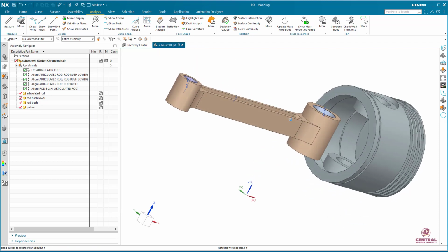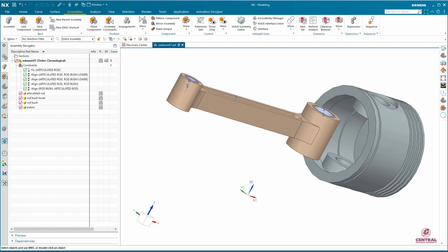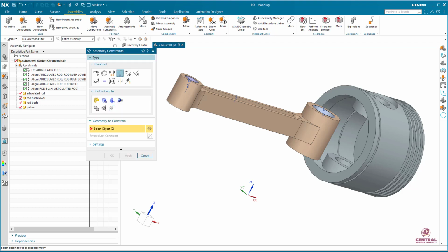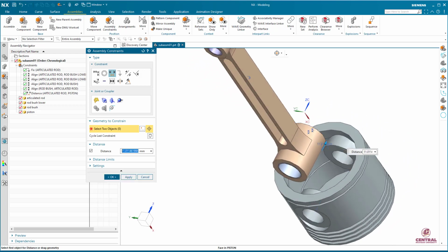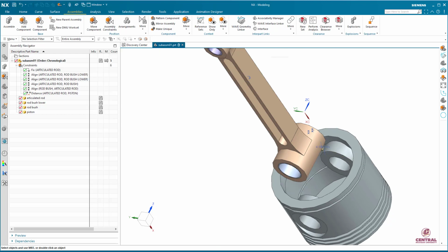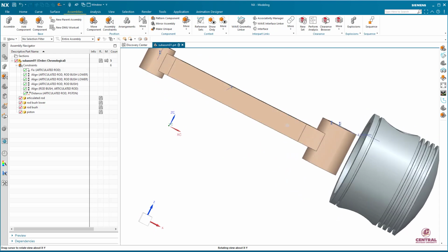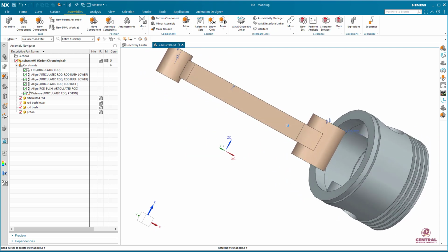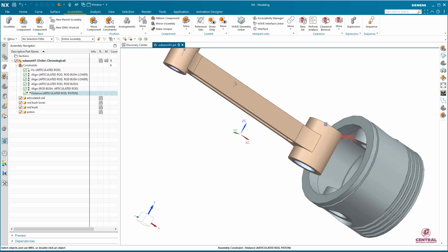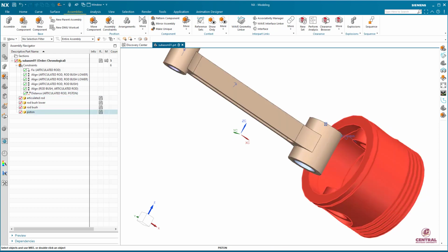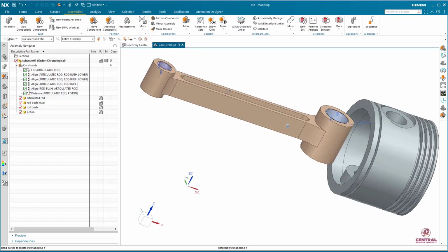All right, so I got the idea. So I am going to go back to the assembly. Finally, add the geometrical constraint. This time, distance, this to this will be 4 millimeters. So 4, enter. Then you can see it. They labeled exactly a 4 millimeter gap, right? Because I already used half of the difference, the other side should automatically be perfectly 4 millimeters as well.